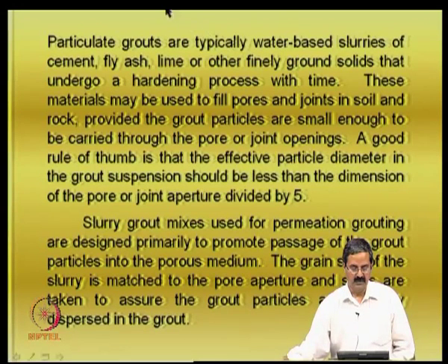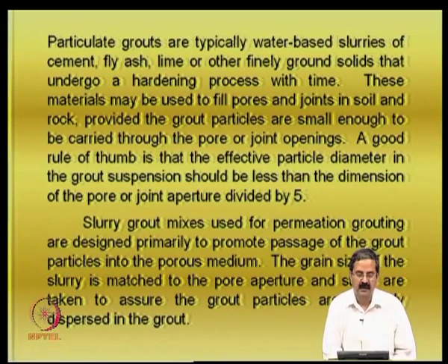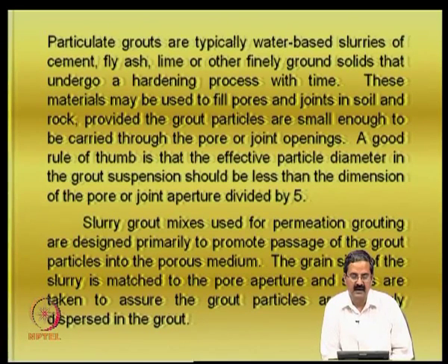In fact, people use many types of particulate grouts. As I was trying to say, the particle size is very important, and it can be cement, fly ash, lime or any other material, and they have a hardening process which is a function of time. Hardening means it sets for some time, then the strength increases if you wait. For example, the shear strength or the unconfined compression strength increases with time,